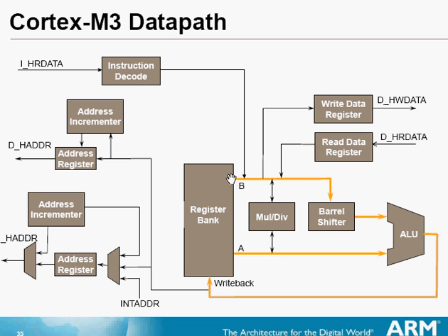The A operand is an A operand. The B operand will go through barrel shifting, and then a new product will come, meaning it's multiplied by 2 to the power 2, right? So it's multiplied by 4. It means R1 into 4 plus R1 will go into R0, meaning total R1 into 5.